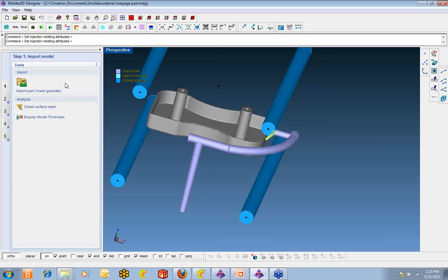Here we see a famous cologne product of Unilever. They took its cover into Moldex3D simulation. For this part, the main problem is heat accumulation near the bottom. In order to cool down this area, additional time would be required at the cooling stage, increasing the cycle time. Moldex3D provides excellent prediction for the high temperature area and the suggestion to enhance the cooling circuit design above the top of the part. After the simulation, the problem has been solved successfully and the cycle time will be reduced